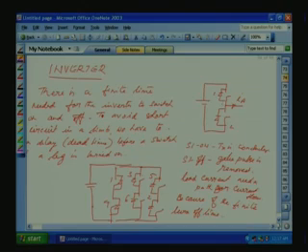For example, in this figure, say one leg is shown here. Let us say S1 is turned on. Now, due to PWM action, when S1 is turned off, we will be immediately turning on S2. Let us take a condition where S1 and S2 have finite turn on and turn off time. That is a practical condition. Even though the S1 gate pulse is removed, S1 will take some finite time to turn off. If S2 is given, S2 will turn on before S1 turns off. So what happens? There is a short circuit and heavy short circuit current will flow.